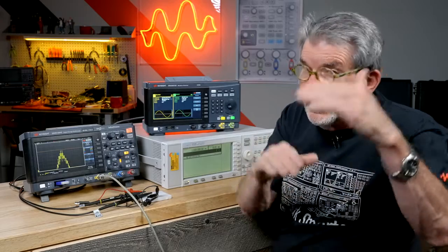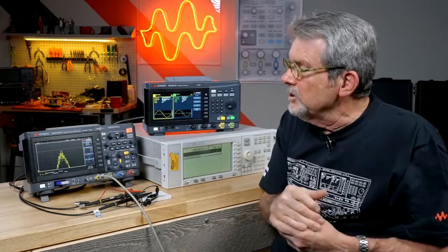Now, that's not the minimum resolution of the scope. If I had started from, say, 5 millivolts per division, then I'd have a different dynamic range, in which case I'd have 200 microvolts of resolution. So, would it be much better with 8 bits or 10 bits?